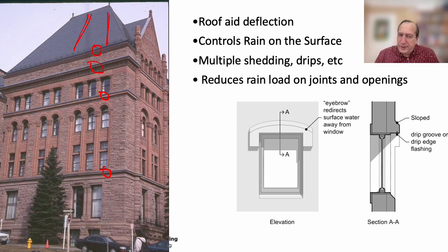Now we're going to start moving into more of the surface details, though. See, this masonry has metal on top to deal with the higher rain exposure. The steep roof would be slate because that's a durable material that can get wet a lot in our climate. The window sills have nice steep slopes. You can see here on the bottom where the slope is more visible.